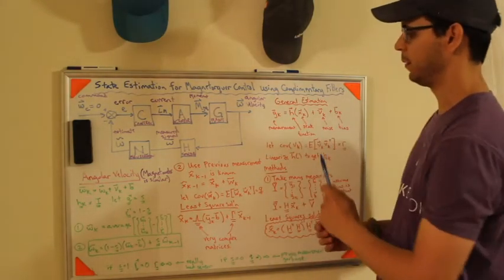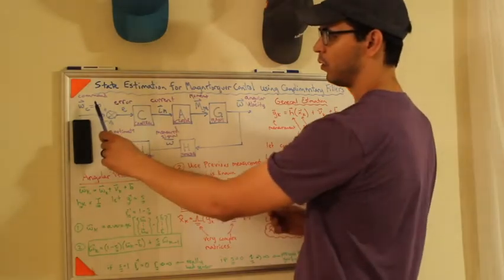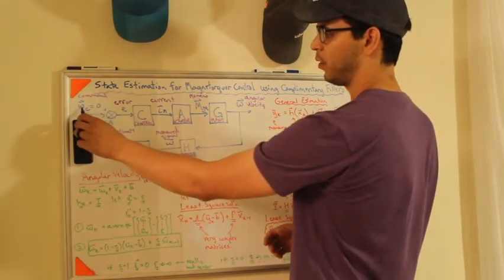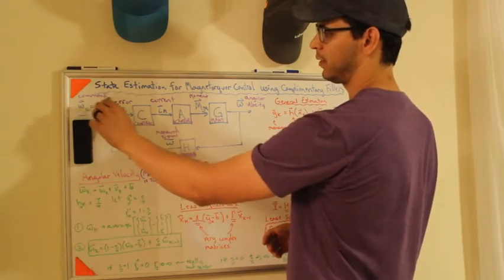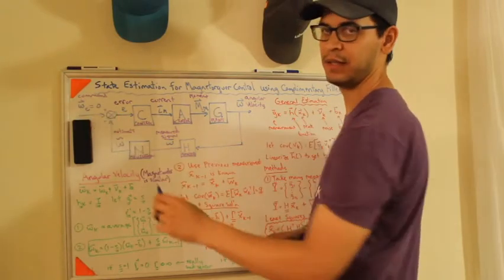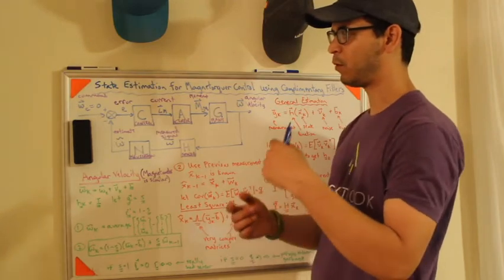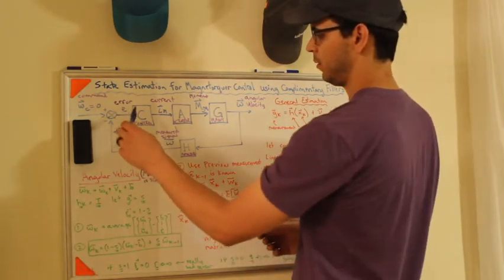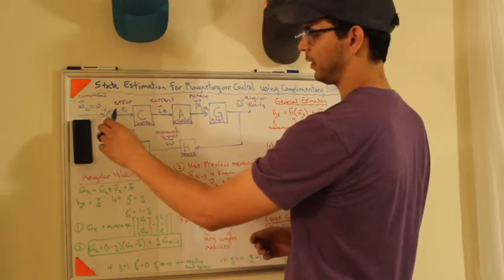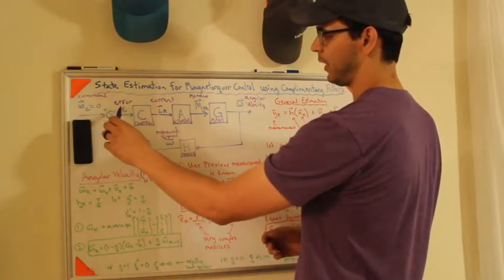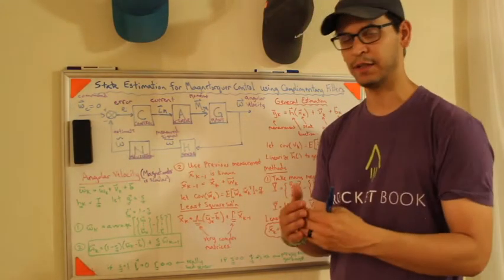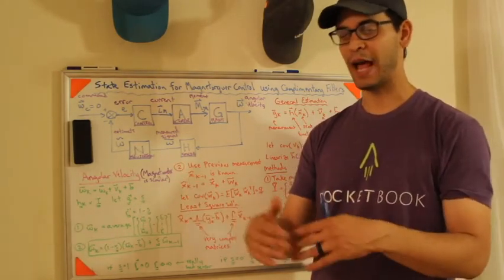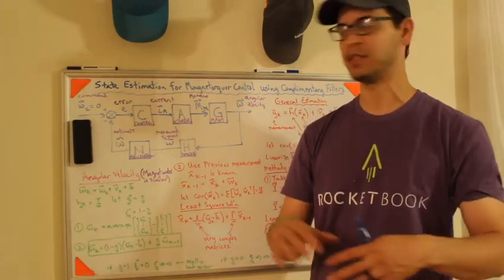And I'm going to use a complementary filter here. Again, I want to slow the satellite down, so what I want is omega command. Omega is my angular velocity, and I want my angular velocity vector to be 0. This bottom block I'll talk about in a second, but basically the error signal is the difference between my command and where I think I am.